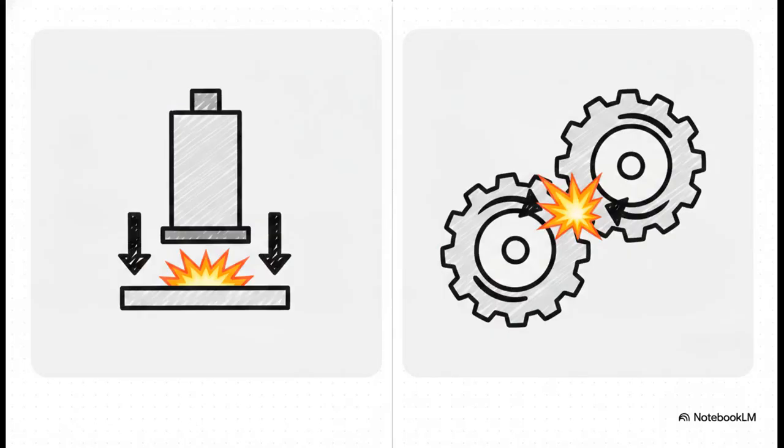Now, besides cutting, you really need to watch out for crushing injuries. These are incredibly painful, totally debilitating, and honestly super difficult to heal from. Crushing hazards generally fall into 2 buckets. First, you've got the squeeze point. This happens when 2 hard surfaces, where at least one is moving, push close enough together to just crush whatever's in between. Think of a hydraulic press. Second, we have the run-in point, which occurs where 2 objects, at least one of which is rotating, come progressively closer together and essentially pull you in.